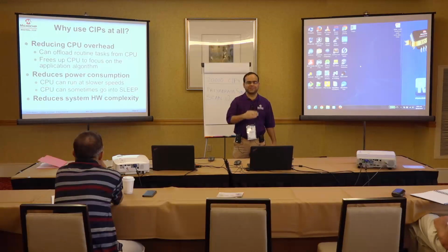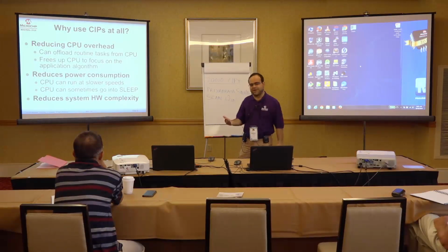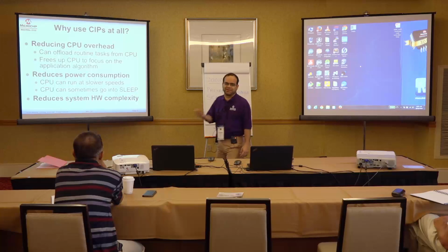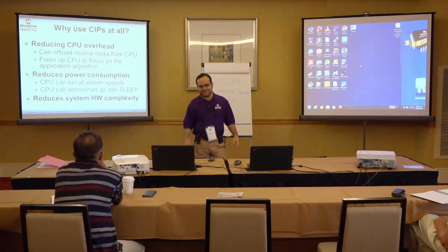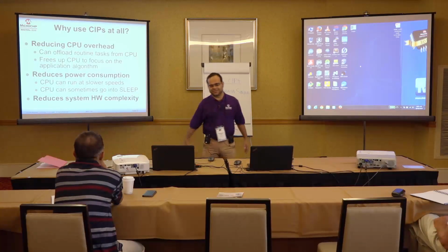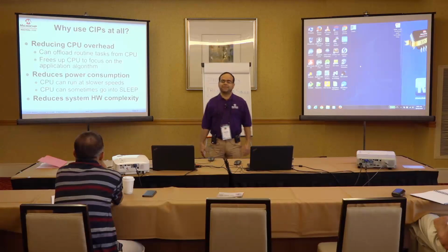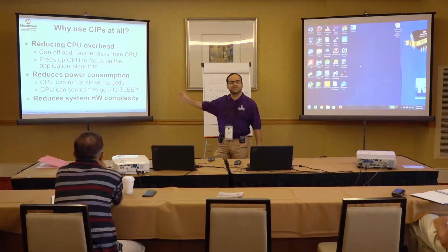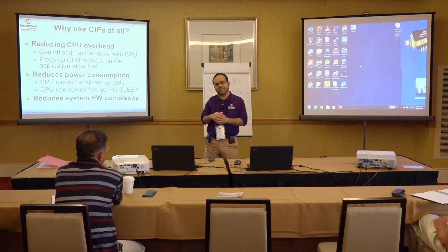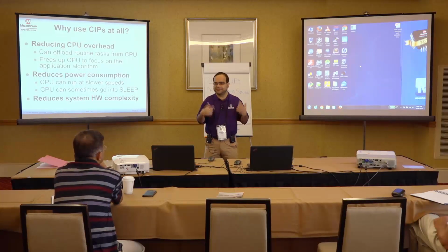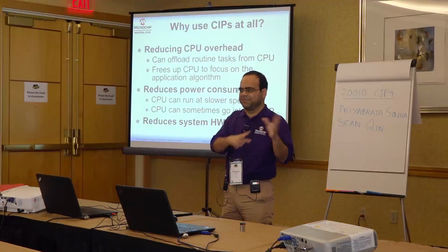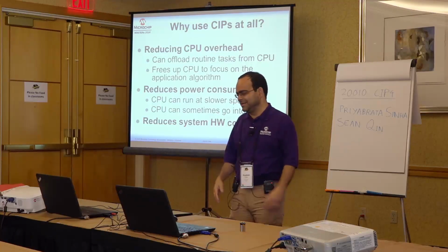So, you can reduce your clock speed, and so the CPU can run at lower MIPS, which means its power consumption is reduced obviously, and CPU is one of the major contributors towards power consumption of any microcontroller. So, if that is reduced, it is really beneficial for your system. In fact, in many cases the CPU can go into sleep and stay in sleep for most of the time and periodically wake up based on some peripheral events and perform some computations as needed.